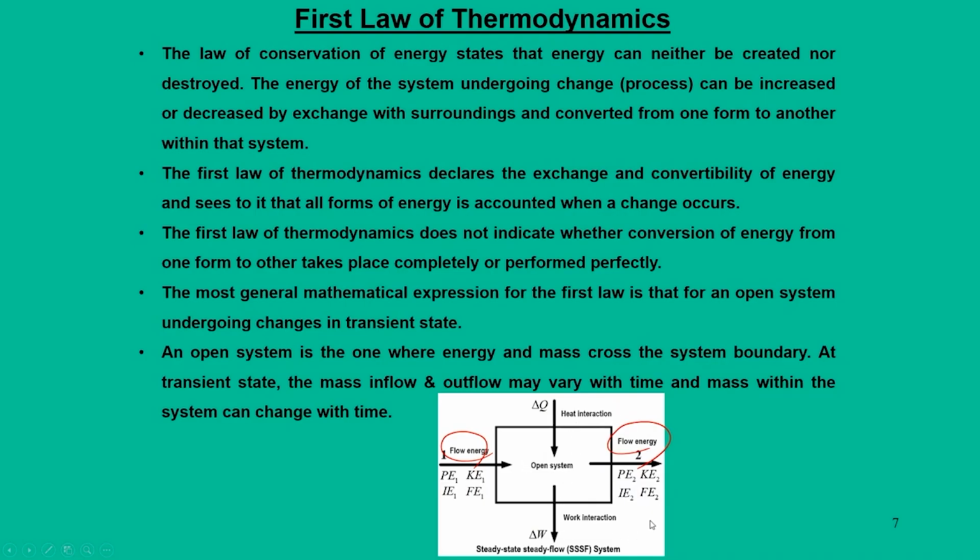Now, the most ideal way of looking at this change of state is that it is a completely transient state, where mass inflow and mass outflow can also vary with time. But ideally, to frame our first law in a very precise manner, we will assume a steady state, steady flow system, SSF system, and for that we are going to see how we need to make this energy auditing which takes care of all forms of energy.